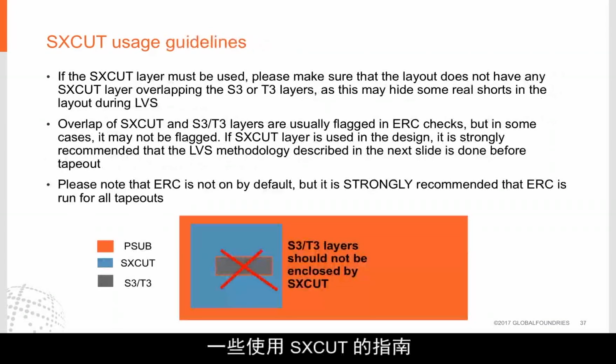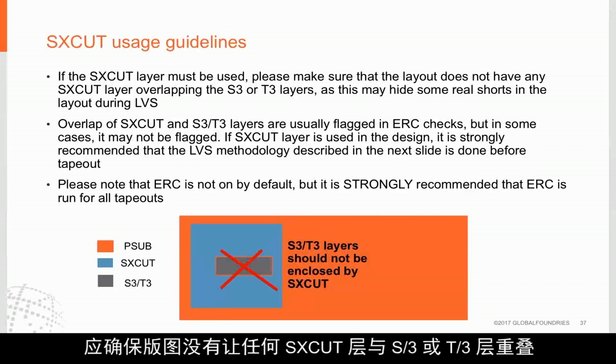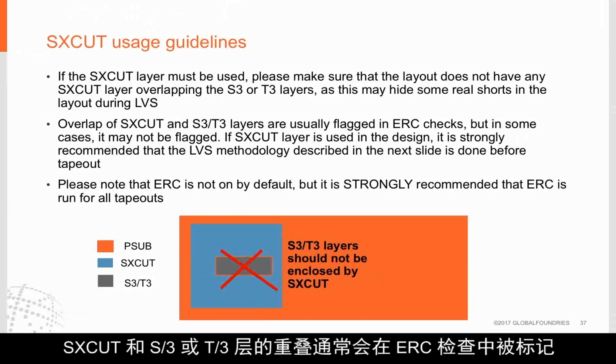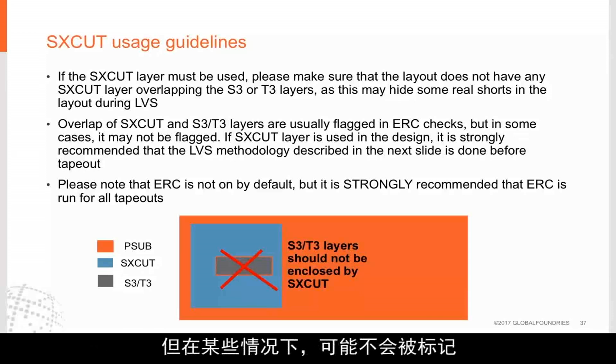Some SXCUT usage guidelines. If the SXCUT layer has to be used, you should make sure that the layout does not have any SXCUT layers overlapping the S3 or T3 layers. The reason is because that can hide some real shorts in the layout during LVS. Overlapping of SXCUT and the S3 or T3 layers is usually flagged in the ERC check, but in some cases it might not get flagged.